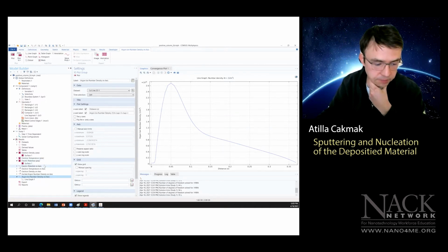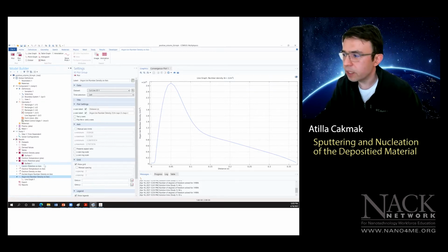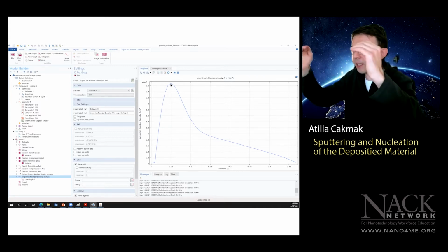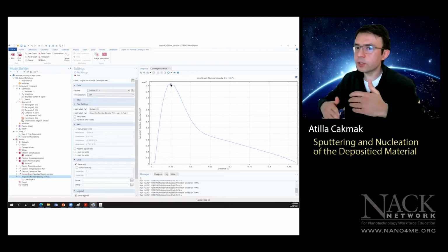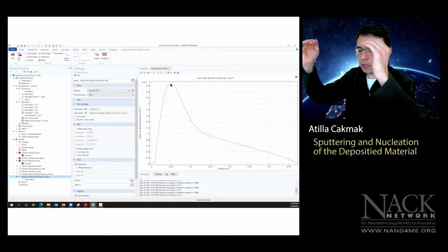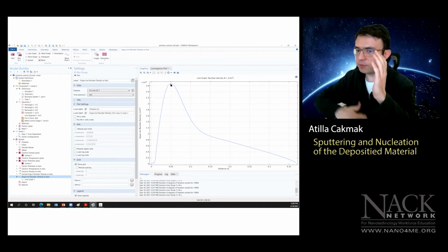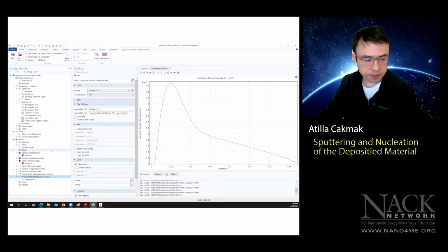So, why do people want that? Why do people prefer a lower pressure? Because a lower pressure means a better chamber, a cleaner chamber, right? And it will also mean a couple of other things too. So you would like to actually ignite the plasma and work with a sputtering tool that's going to come down to a lower pressure if you can afford it, of course. Like 500 millitorrs is really very high, our initial value.